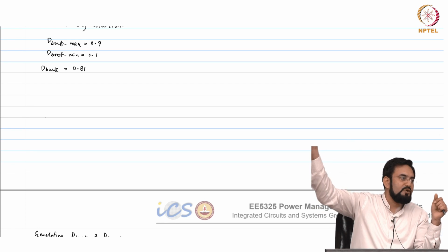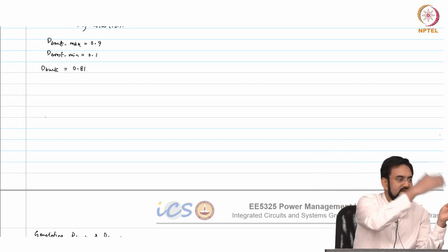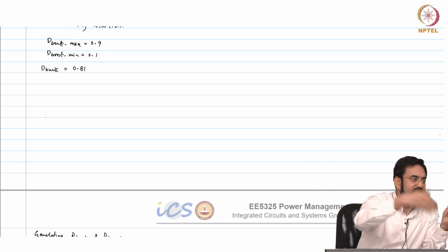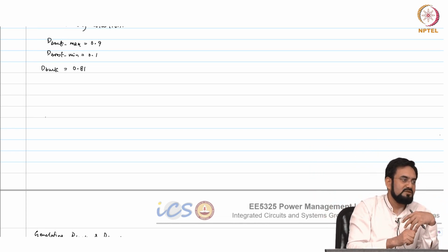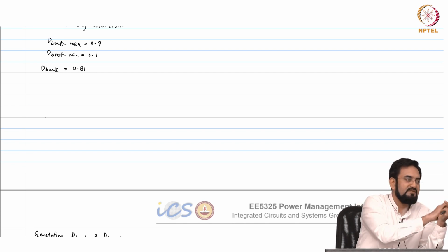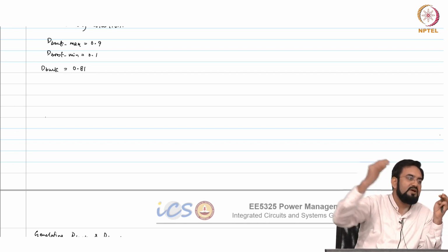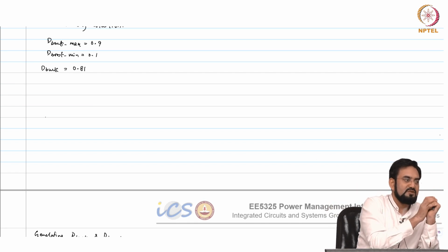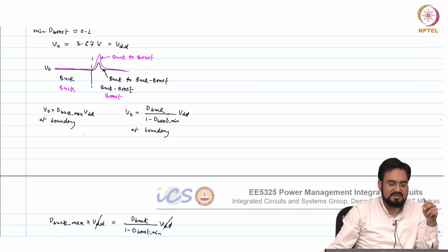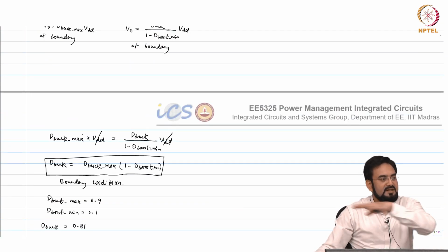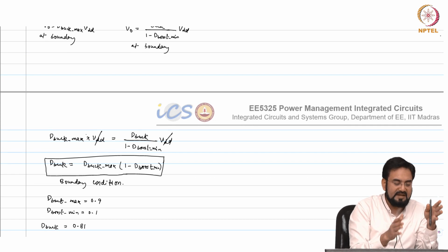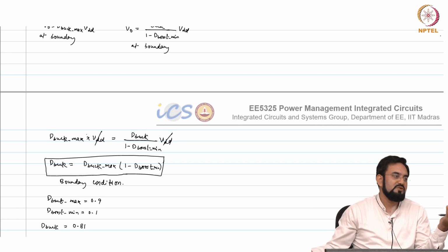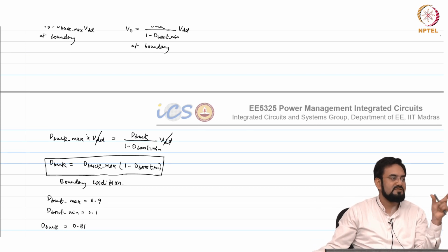Let us say you go to 0.2 or so, then you can change the buck duty cycle to 100% and move your boost back to around 0.1 or so. You can calculate again with the boundary condition at what boost duty cycle you actually want to force buck to 100%. In that case your high side switch in the buck will be always on, and you will be entering the pure boost mode. Otherwise, you will always remain in buck-boost mode, you will never come out of that if you saturate your buck duty